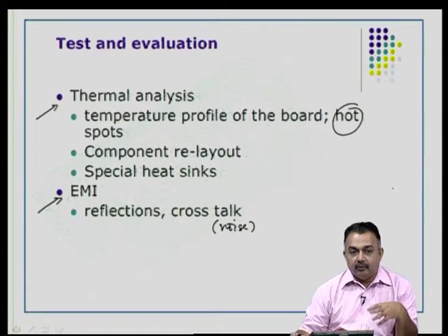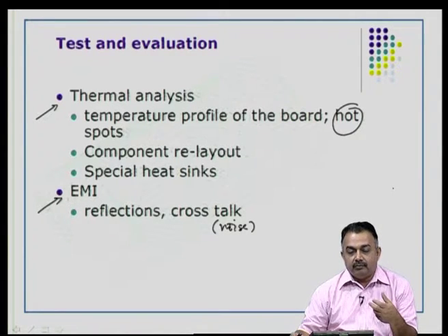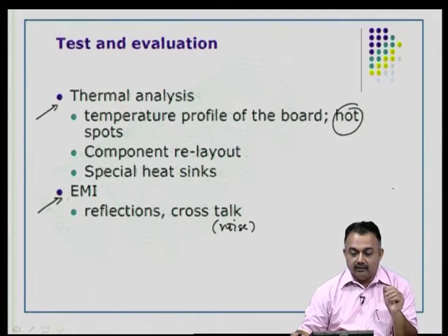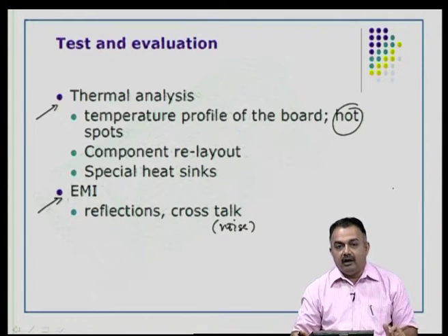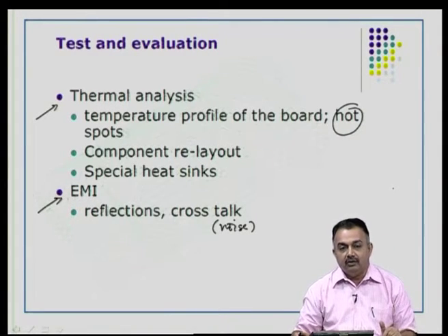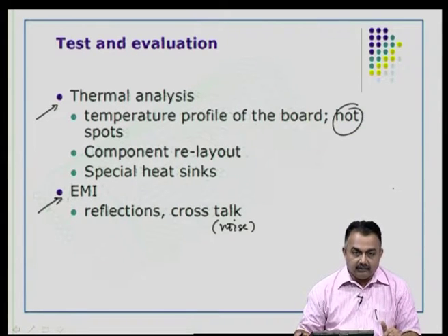Okay. If you are grouping 3 ICs together and all of them are going to dissipate, let us say 25 watts, and that needs to be dissipated quickly, but you have not provided enough mechanism, then you have to take care to make sure that you separate these devices far away and also provide additional cooling mechanism.